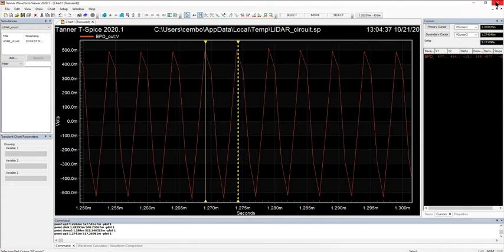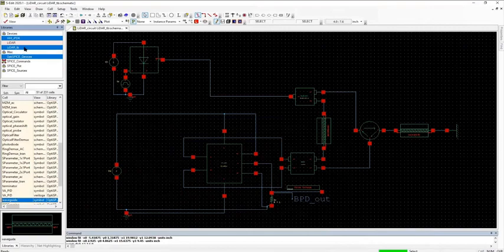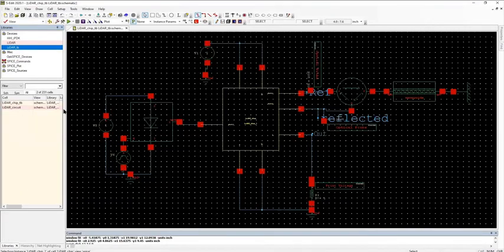Now let's go and look at the simulation results from the chip itself that we extracted from the netlist. Again, you can see the inside of the chip is modeled by the extracted netlist, and the externals of the chip are still modeled by OptiSPICE devices. Again, you can just hit run and look at the simulation results.